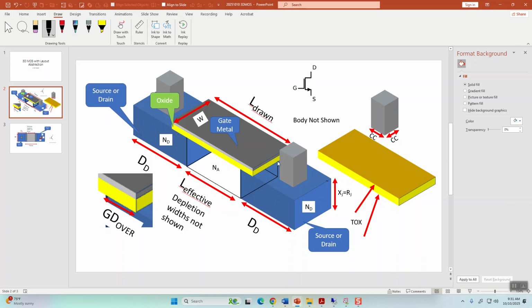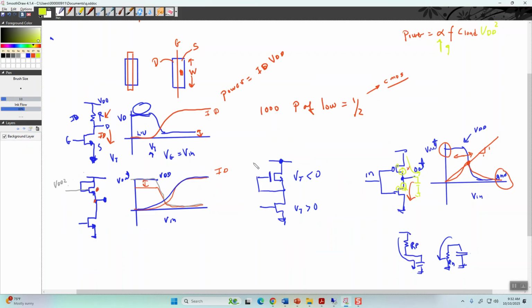But by scaling the voltage, the power is reduced, but also the power density can stay close to the same. Now, as we've been able to scale, you were able to increase the frequency. The devices are smaller and they're faster because the load has gone down. But really, the power density has kind of hit the limit. And so now you try to do things in parallel. All right.